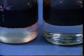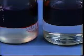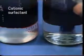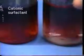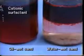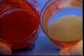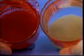Surfactants can also alter reservoir wettability. Here, 2 beakers contain identical samples of water and oil with a red dye. The beaker on the left also contains cationic surfactant. Water-wet sand grains are poured into both beakers. Red-colored sand indicates grains that have become oil-wet and illustrates the change in wettability that occurs from treating anionic sandstone with cationic surfactant. In the reservoir, this increases the residual oil saturation near the wellbore and reduces the permeability to oil.